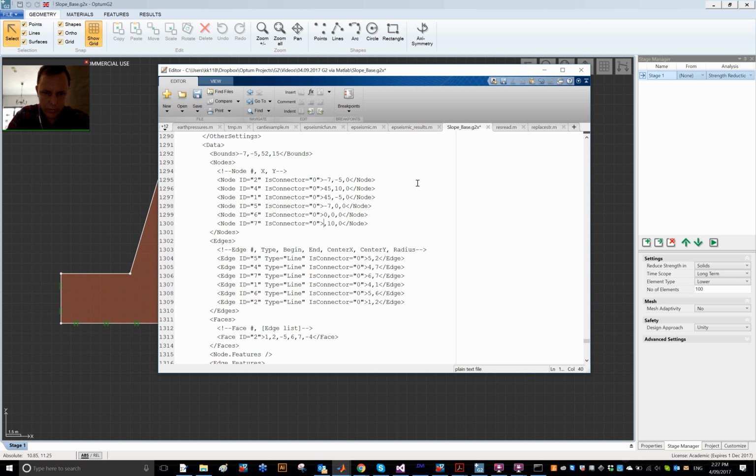Instead, what I'm going to do now is set things up to have this change be done in an automated manner. So I'm going to define a variable, and I'm just going to call it x. I'm going to enclose it in dollar signs. That's totally optional. That's my own personal preference. I know there are no other dollar signs in the input file, so whatever I enclose in dollar signs is going to be a unique string.